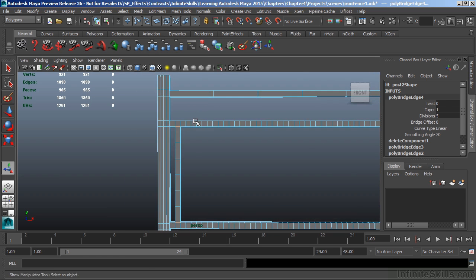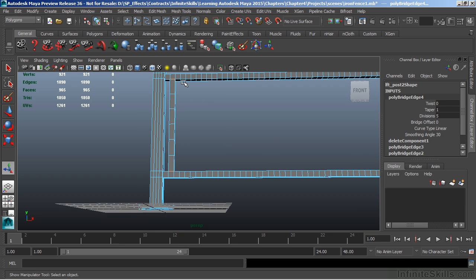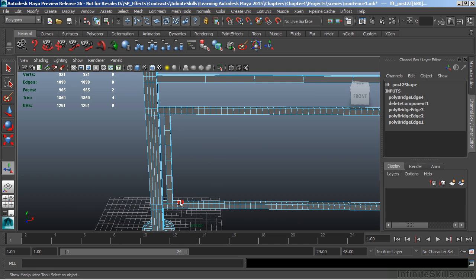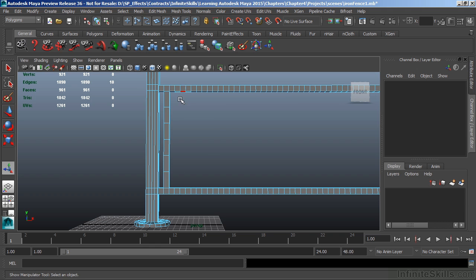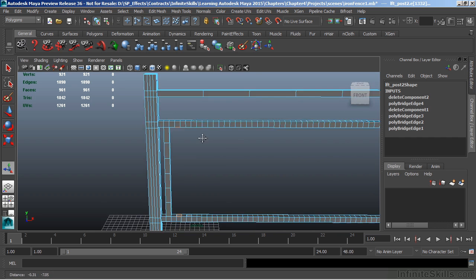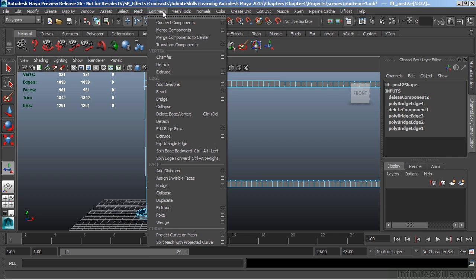And we'll add a bridge. Let's continue on. Let's add something a bit more unique as we go here. Going to select that face and that face. And grab that one and that one. And delete both of those. And we'll switch to Edge. Double click. Double click. And now we'll do a bridge, but this time, let's change some of our options.